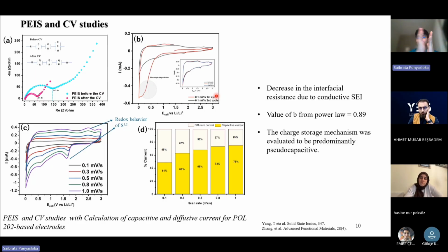SEI is very important because once the electrons come here, they cannot pass through this SEI. The electrons come into the battery from the outer circuit and cannot pass through the SEI, so more electrolyte reduction doesn't take place. That is a very important characteristic of SEI.